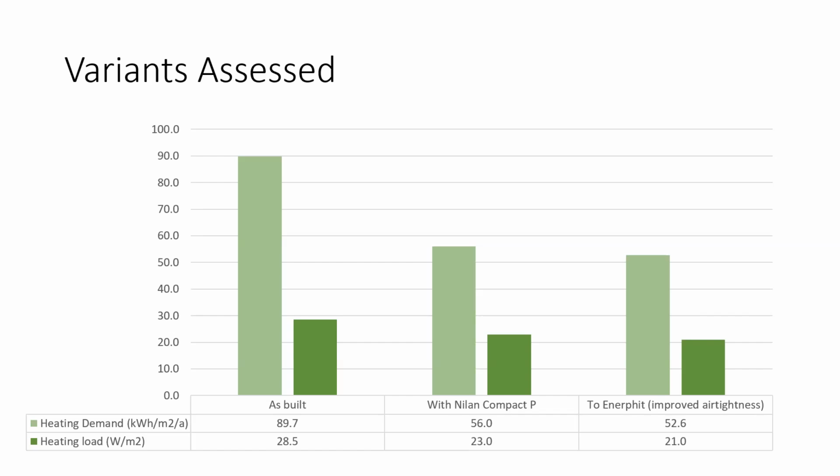The Passive Institute insists that you have an MVHR system, so that you're supplying warm air rather than air at whatever the outdoor temperature is on a given day, a much more controlled internal environment, and your improved air tightness, which would be one air change. So if you have both of those performance criteria, this particular building would achieve Retrofit by the component method.